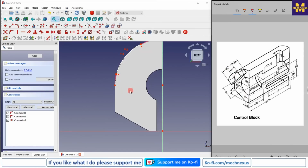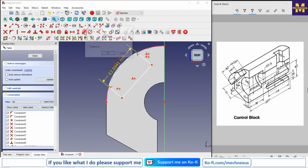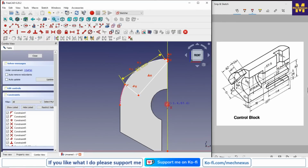And overall it is 82. So I will create a line and join it with these two lines. I will add parallel, and this one will be the perpendicular. Okay, and now I will give the dimensions, which is 82. Line, and I will make it construction.